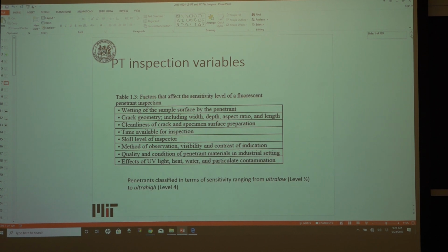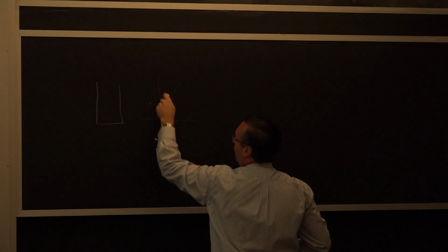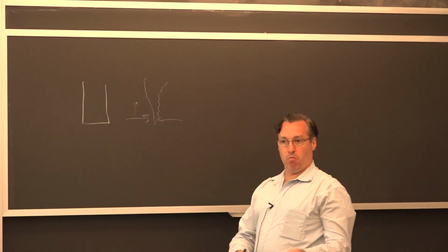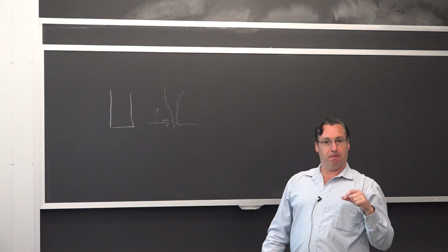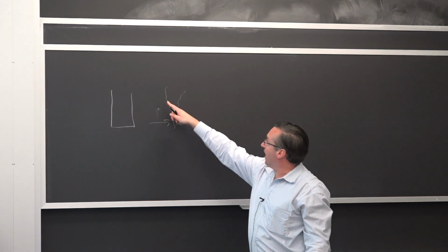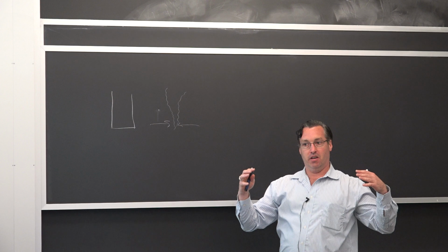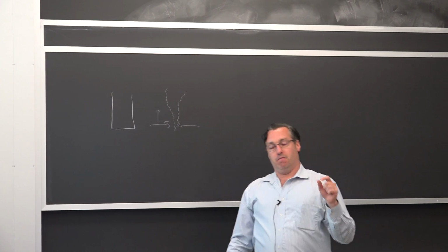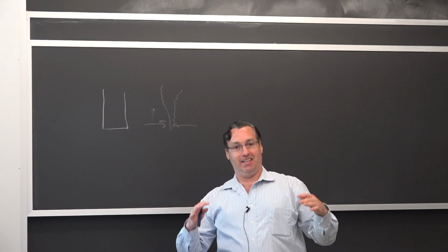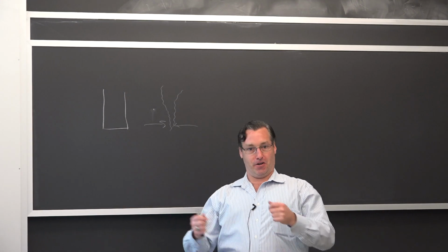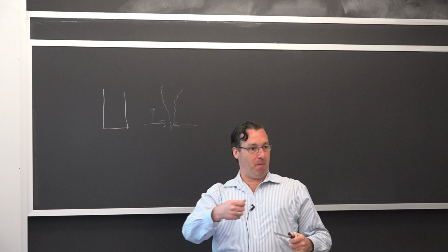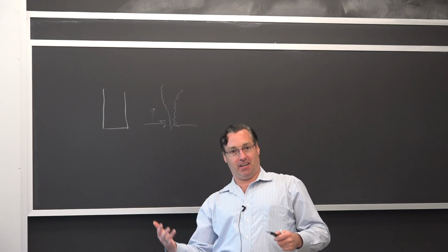In real life, the crack will take some type of tortuous path, so the aspect ratio from the surface to the bottom, that is what I'm talking about with aspect ratio. In real life, the flaws aren't flat like this. They have various orientations. And if you deal with NDE as much as me, I read a lot of cut sheets or vendor manuals on what they claim they can detect.